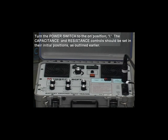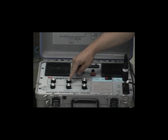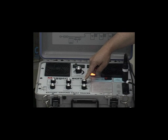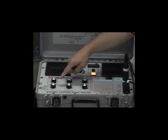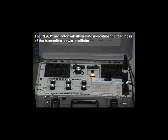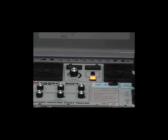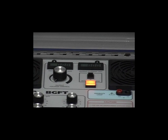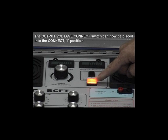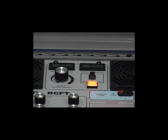Turn the power switch to the on position. The capacitance and resistance controls should be set in their initial positions as outlined earlier. The ready indicator will illuminate, indicating the readiness of the transmitter power oscillator. The output voltage connect switch can now be placed into the connect position.